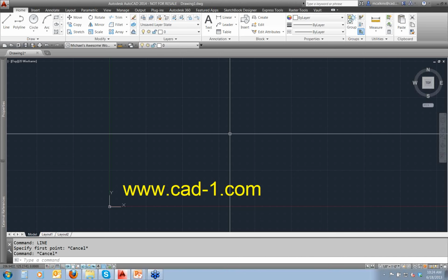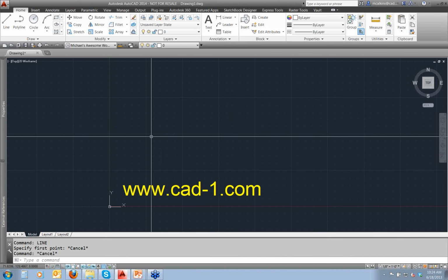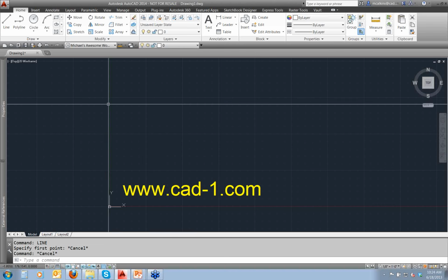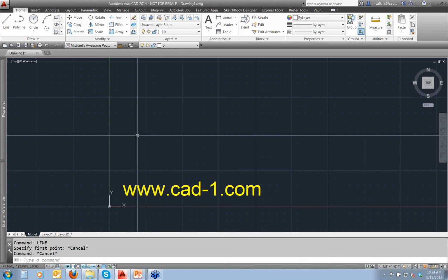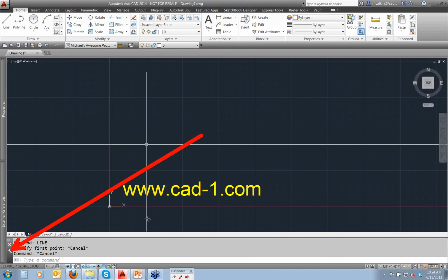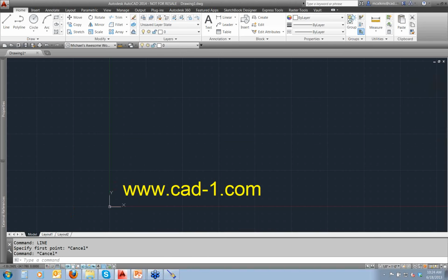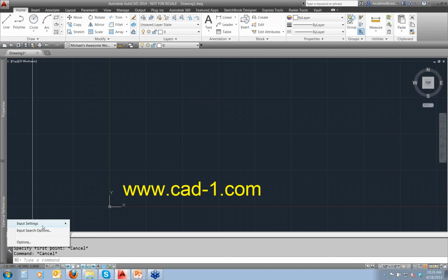You don't want that functionality interrupting your view here on the screen. We can control those. We have options for the auto append and for the suggestion list. And there's a couple ways to access those settings. One of which, or the easiest to see right away, is this wrench on the command line. Make sure not to hit the X because that hides your command line. Click the little wrench down here where it says Customize, and you'll get this list of options.